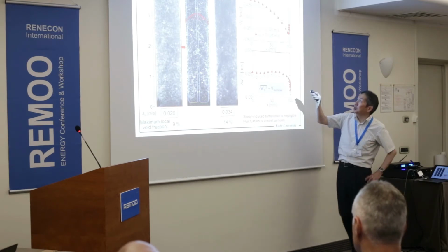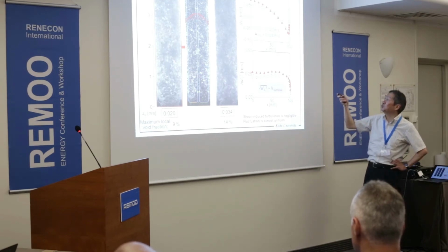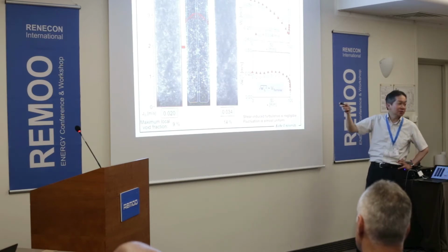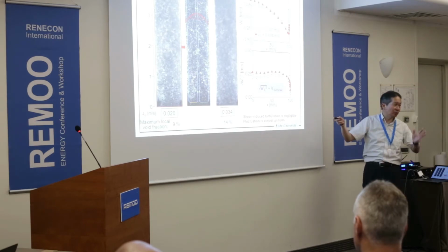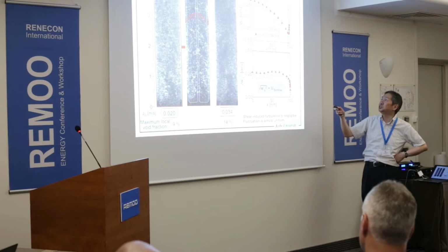And these are the measured mean velocities. We have a negative value here because the flow is circulating like this. The mean velocity field has a negative value in the vicinity of the column wall, and here we have the higher velocity. Depending on the gas flow rate, we have different velocity distributions.